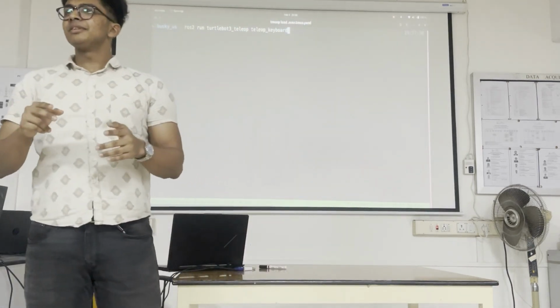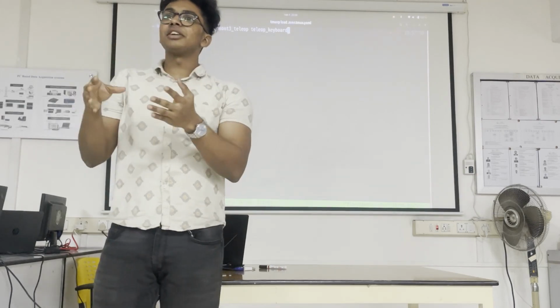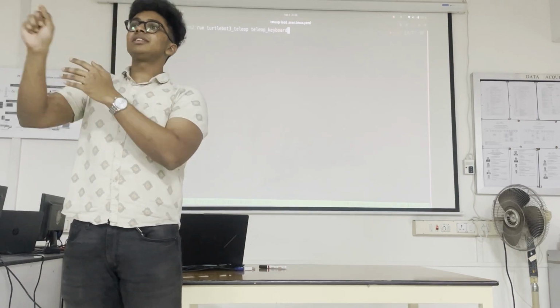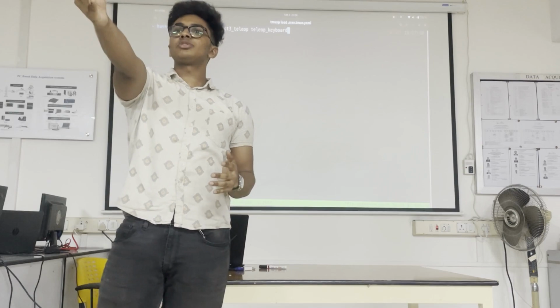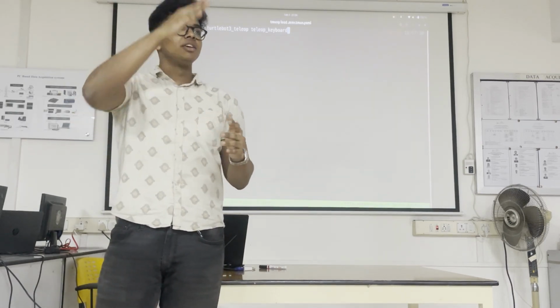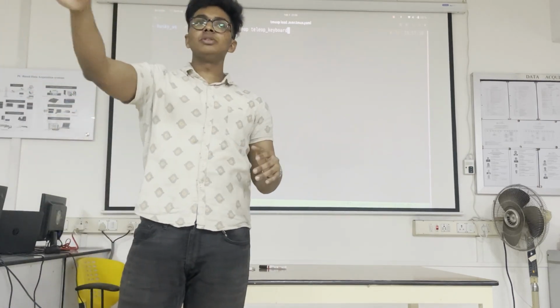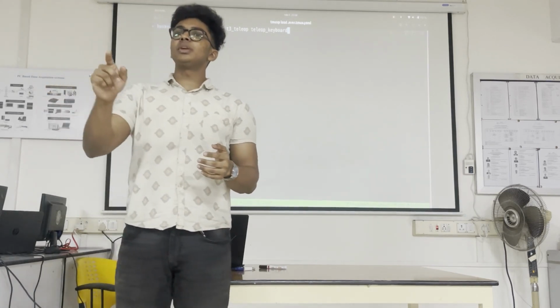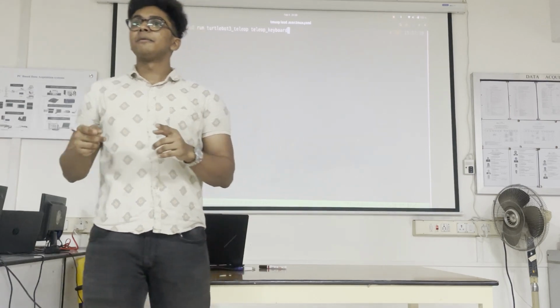Yeah. So, the thing is, the simulation which you are running, right? If you notice, when you press a key, the bot starts to move. That actually happens via pub-sub. The keyboard node is publishing something called command velocity. It's sending a value. If you do ROS2 topic list, you'll find all the topics which are being used right now. Just try that out. In another window, do ROS2 topic list, you'll see all the topics. And if you do info for any one of them, you'll find out how many publishers, subscribers, and what type of messages are in that.